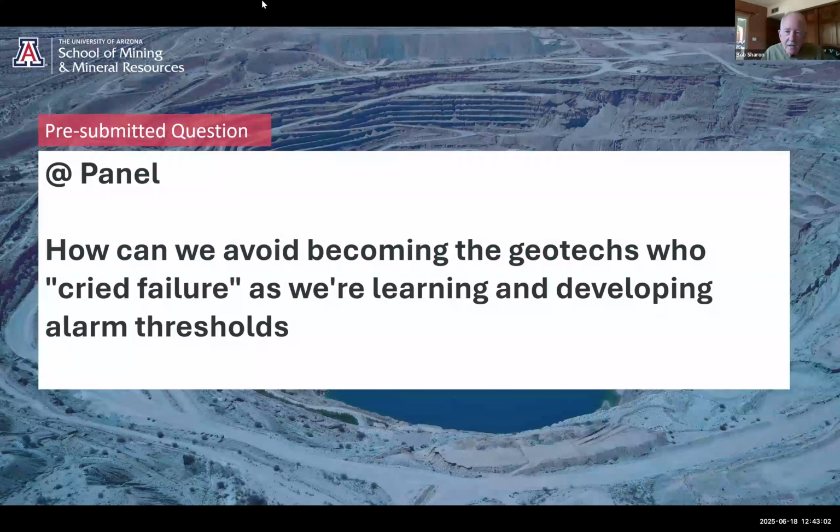When you're working in a mining environment where you do have slope movements and you have a close call or two, you're getting some really good real life experience from this. I think there's a point in there where you want to run a trial of how your alarm system works. Are your TARPs really working?